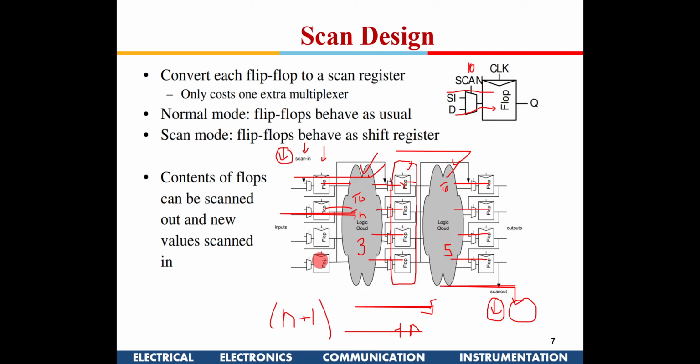In such cases there won't be economy of effort, because every combinational block will be unique in nature. So if we have access to these sets of flip-flops separately, and I can put data into these flip-flops directly, then it is better. It does mean creating additional hardware, but the total testing time requirement might reduce.